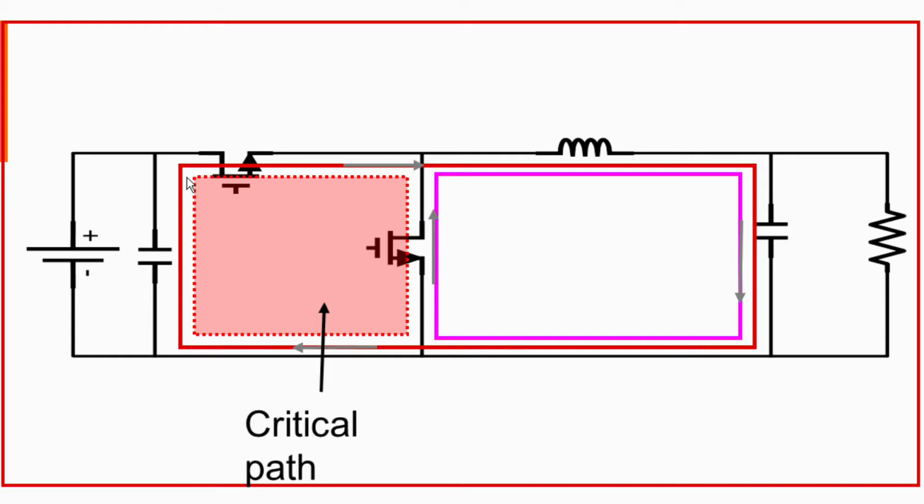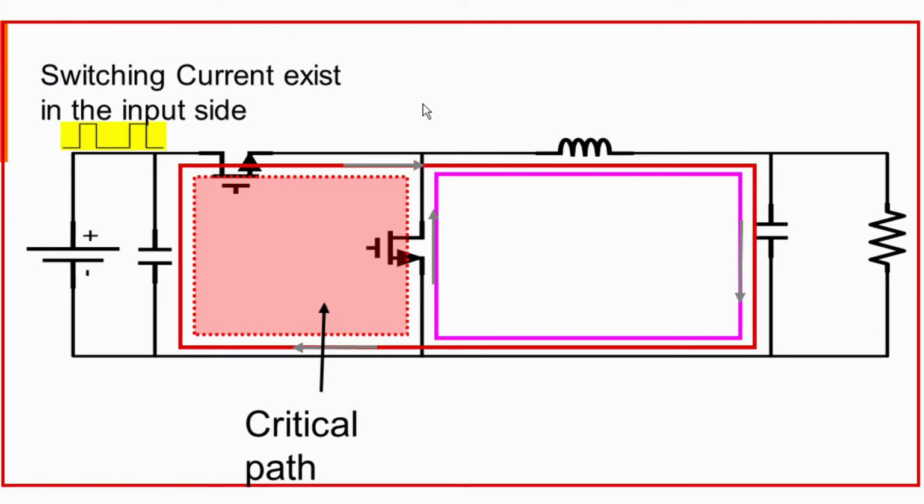Another way you can get radiated noise is this pulsed current going down a long input wire. That pulsed current down a long input wire is also an antenna. And also, if you look at the shape of this pulse current, this node here is creating this chopped pattern. That chopped pattern is fairly high voltage, and that can capacitively couple to your outside system.